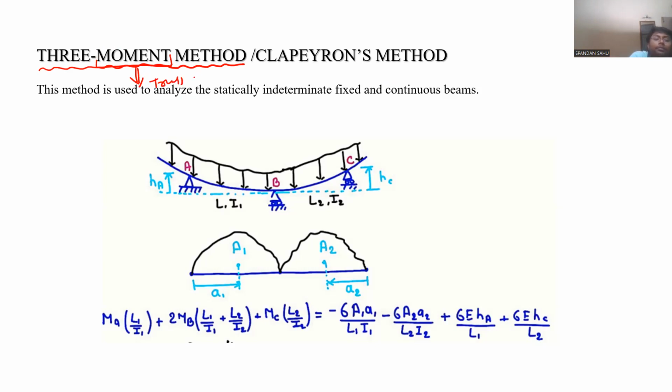No, sir. Why no? Because normally shear forces and bending moments are not generated in trusses. Truss members are axial members. They won't take any shear or moment, so there won't be any shear force or bending moment. Yes, correct, sir. I agree. If we try to bend the truss, then it will simply break.